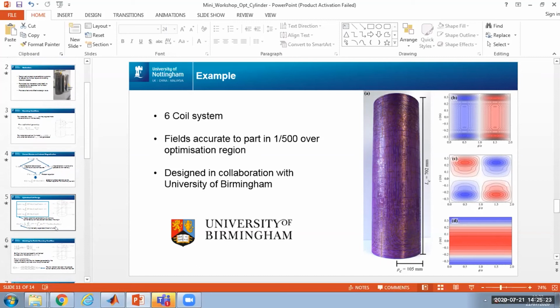With respect to the actual experimental validation, I personally don't have much experience. I'm mostly theoretical. But with all of the coils that we've tested and physically made, we can see the effect of the end cap, and the effect of the holes in the end cap. They do affect it, but you generally see a meaningful effect at a distance of the order of 2 times the diameter away.